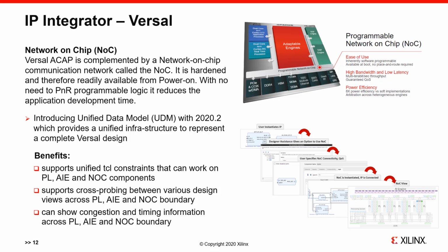With 2020.2, we are introducing UDM, which presents a view at higher abstraction, particularly for the AIE and NOC components, which are user-friendly. It provides an integrated view for complete Versal design that includes programmable logic, AIE, and NOC components. Some of the benefits include support for vertical constraints, support for cross-probing between various design views, and it can also show congestion and timing information.